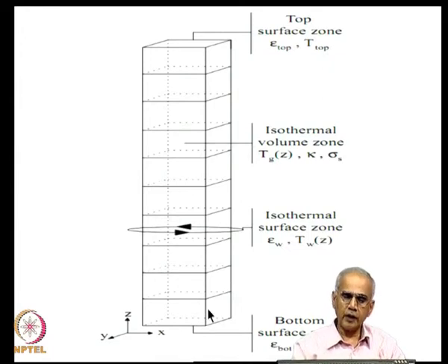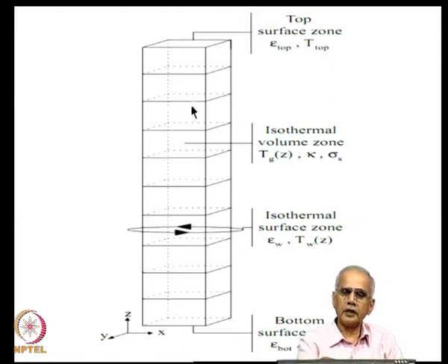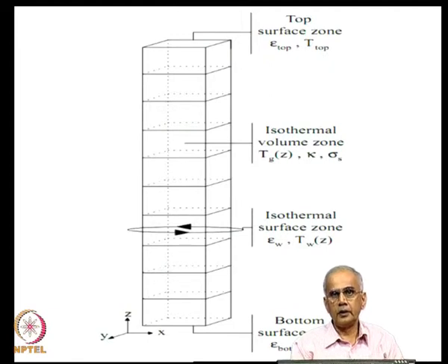What you can do is divide the furnace into many zones and treat each zone as isothermal and apply the well-stirred furnace model for each, and then link it to the next and next until it comes to the exit. So, this is an extension of Hottel's 0 dimensional well-stirred furnace model to 1 dimension, by having a series of 0 dimensional models linked together by a common temperature.